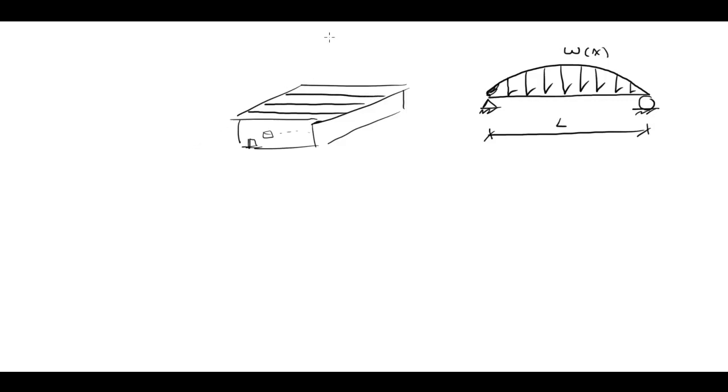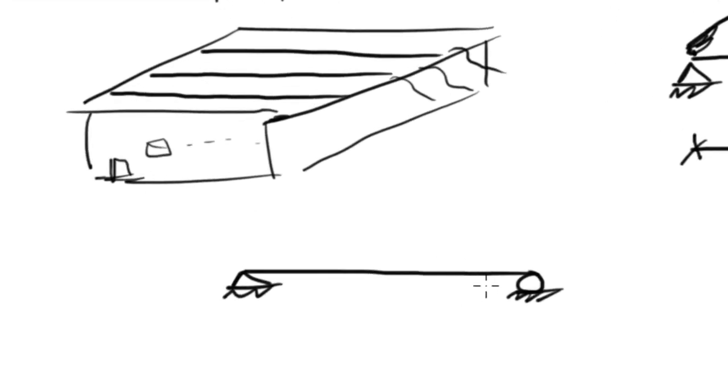Let's say it was raining, and what happens to this beam? If, and only if, you don't have adequate drainage that gets rid of the water, what will happen? It will start deflecting like this, and moreover, water will be trapped right here.